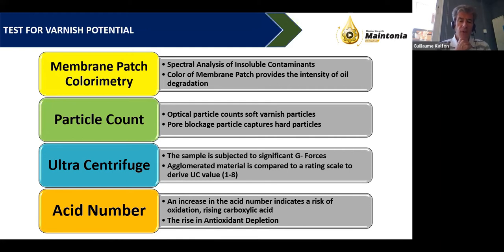So it's the same for the phenomenon of oil degradation and of varnish. And you can hear that I'm spending a bit of time on this point. It's the heart of the matter. It's a pivotal point. To avoid this problem, or to catch it early enough that you can still have time to fix it before it gives you a problem in your production, you need to have the right oil analysis. You cannot manage this issue if you don't get the right oil analysis.